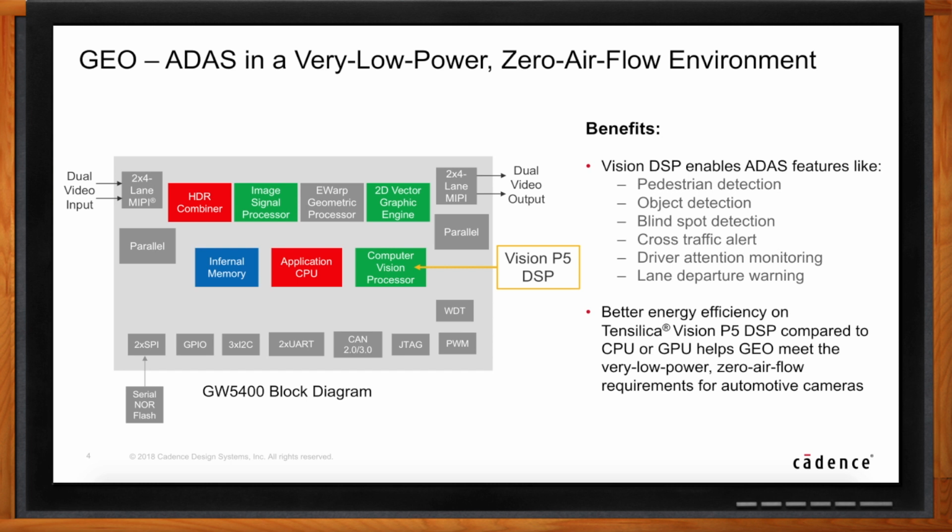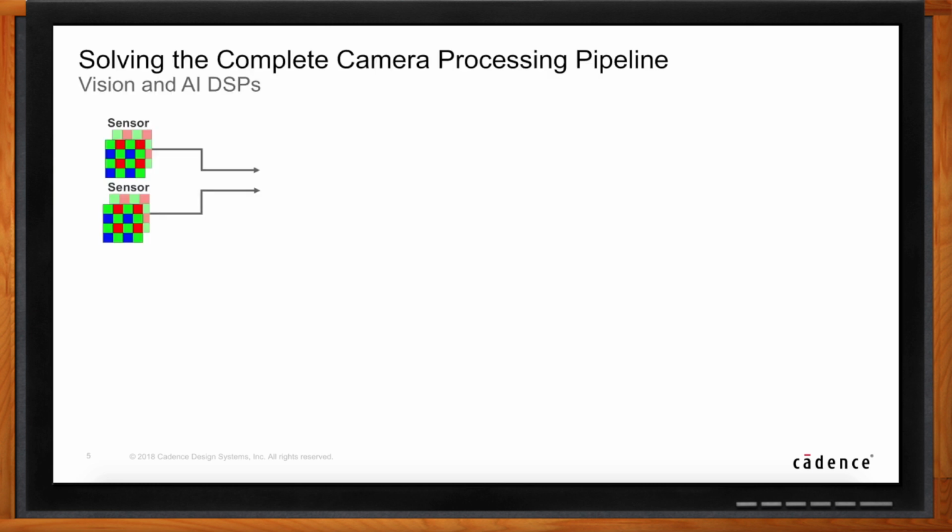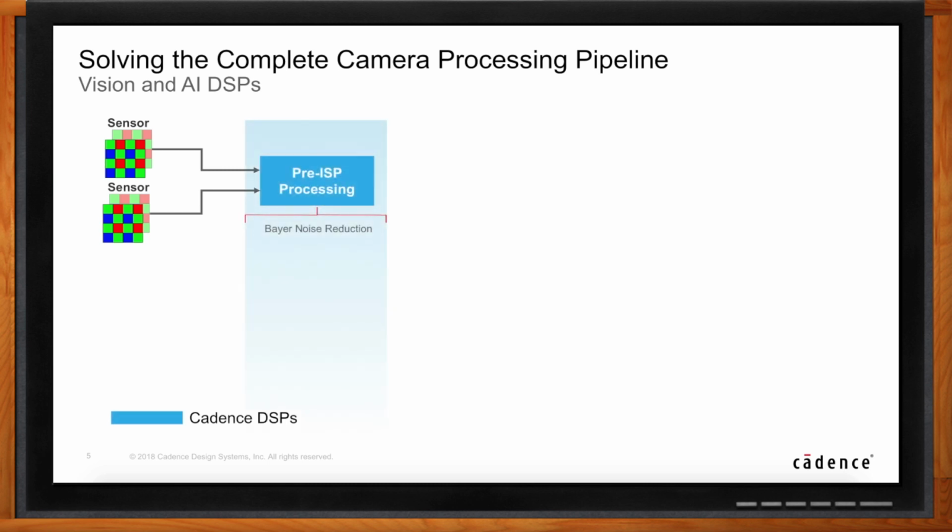Now, can we take a look under the hood and see how the data flow is typically put together in these kinds of applications? Yeah, so we are primarily looking at connecting in a pipeline where an image sensor, which is also called a Bayer sensor, is used. If you go from left to right, information comes from this sensor in what is called a Bayer format. Usually our customer will use it to do noise reduction in that Bayer format, and usually when the pixels are very small, 1.1 micron, 1 micron, 0.9 micron, this is where our customer will use it. Then the ISP converts Bayer into RGB or YUV, and usually our products are not used for that.